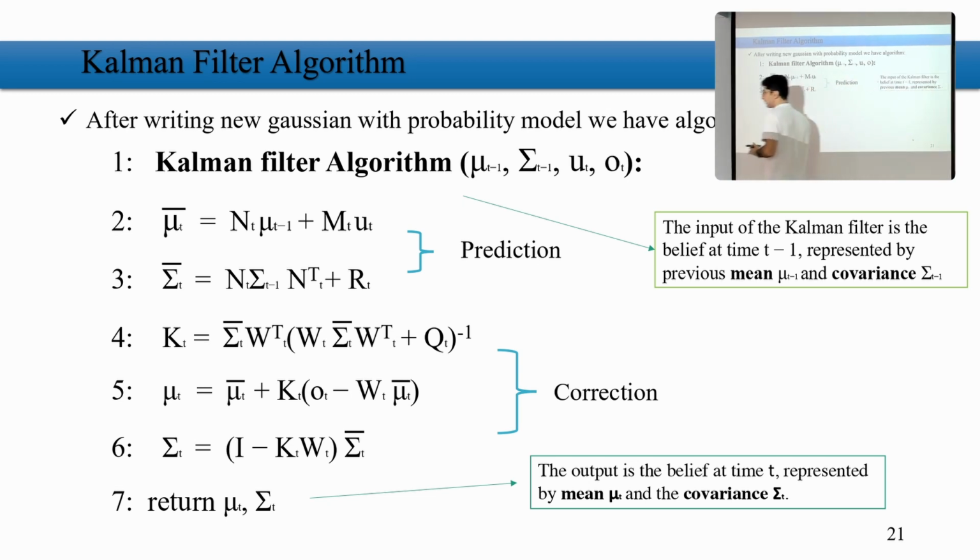And we say, okay, with mean and covariance, I indicate the initial belief is there. That goes into the algorithm of the Kalman filter. And of course, the control command and observation are also inputs for the Kalman filter. That can be done in an online way, where each time I'm sending to the Kalman filter, or if I have all of them, I send them, depending on the implementation that we have. But still, in the loop that we have, we will update it each time, just predicting and updating, two steps.